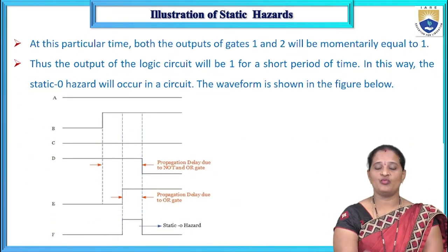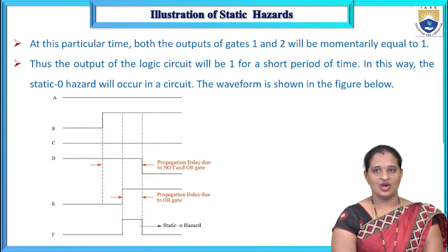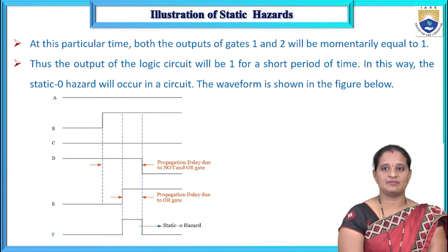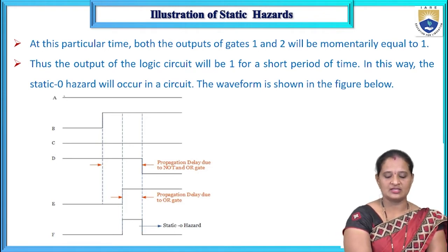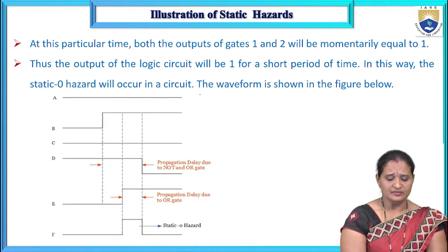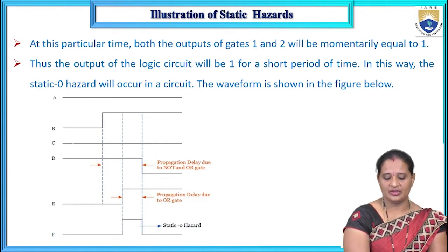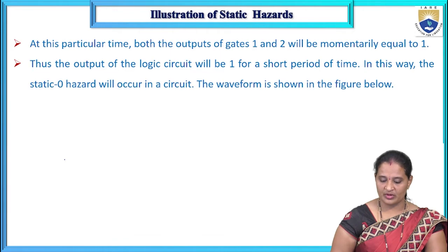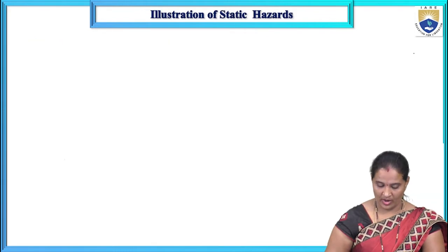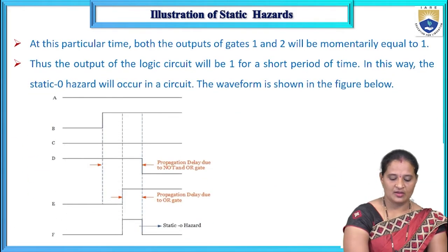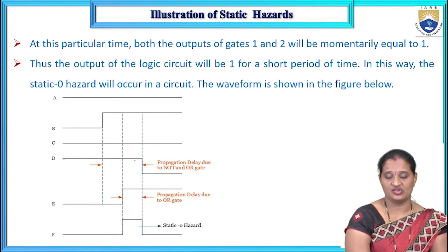So this is how we can detect the hazards here. Now I want to explain these hazards in a graphical way, that is, using waveforms. Let us consider A equals 0, B equals 0, and initially C equals 0. When A is 0, B is 0, C is 0, what should be the output of D? This is the circuit, right? When A is 0 and B is 0, the output of D, that is OR gate 1, becomes 1. So here the output of D is 1 initially.